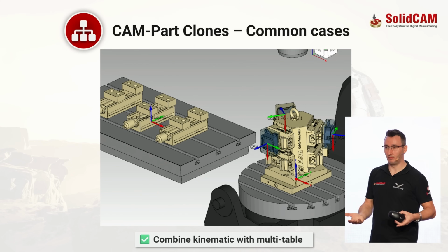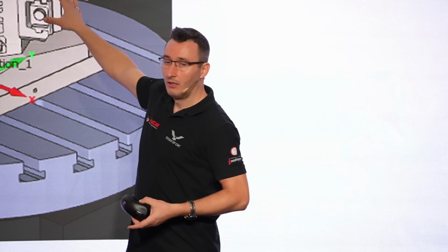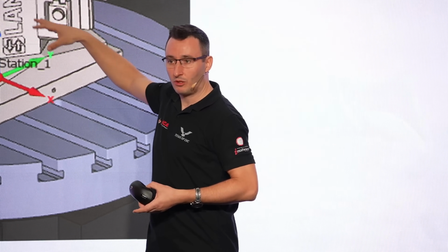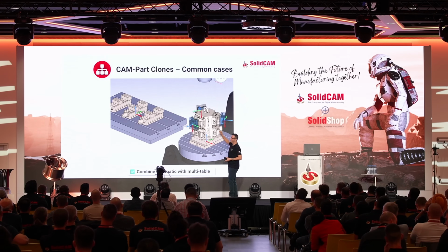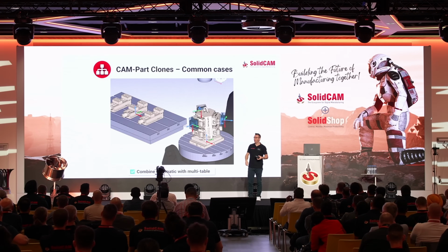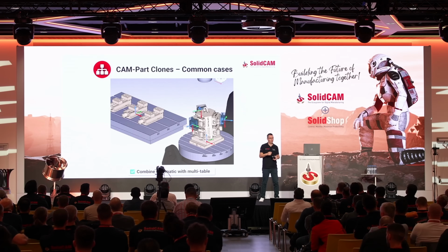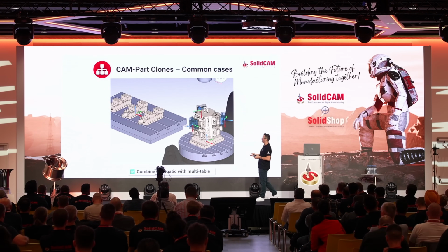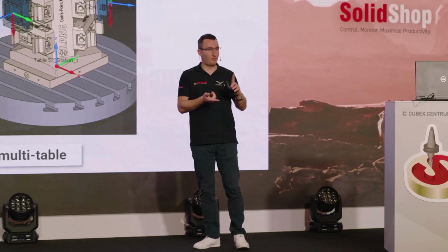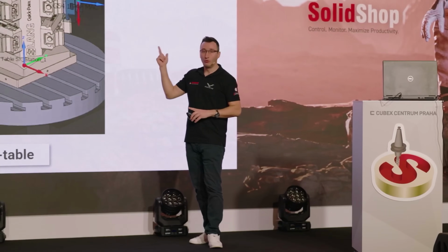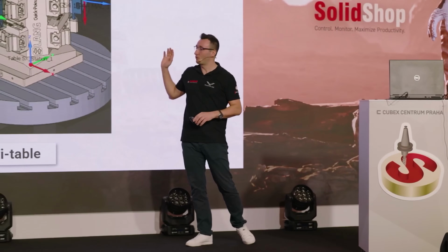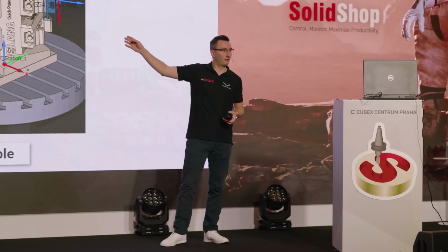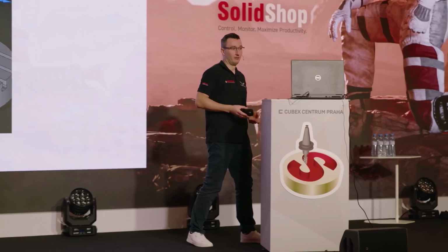When you load machine simulation, you'll see updated stock of all these workpieces machining there, and also you have the 3 clones with stocks there. Optimizing the tool change with a single click, which Michael showed just a few moments ago, sorting, optimization sorting. We will analyze per each workpiece the tool change, what is possible. We'll analyze the angle change. So we will try to give you the minimum machining time for these workpieces automatically.